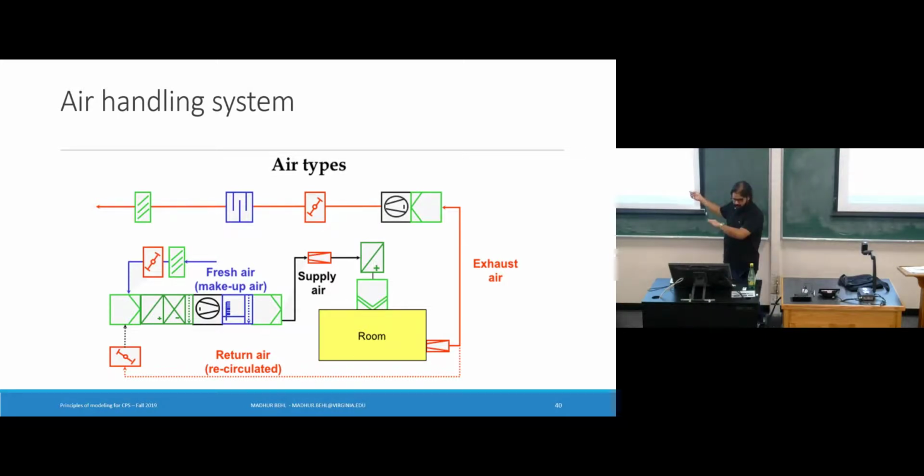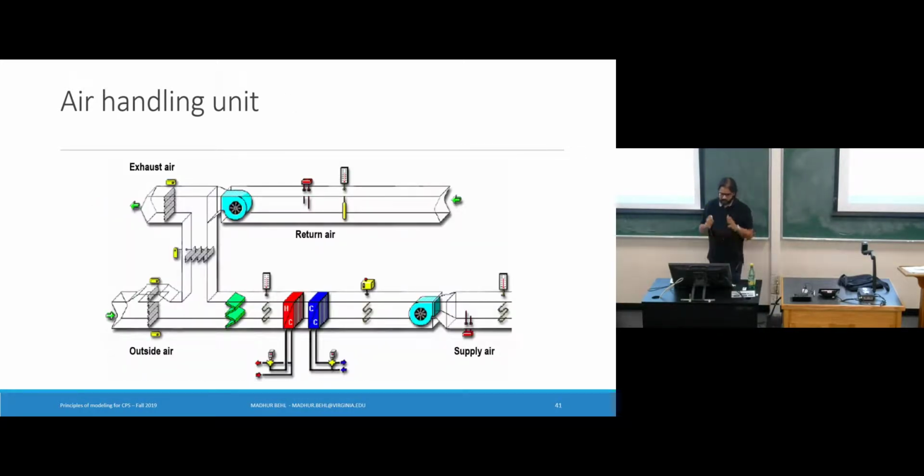So the same story, but in 3D or more detail. If we break down the air handling unit itself, again, outside air comes in. How do you actually condition the air is the next question. So let's talk just about temperature first. Inside the air handler, there are some heat exchangers or coils. So let's say we want to cool this air. What is happening without us realizing is that inside every air handler, we are continuously circulating chilled water. So this is the first transfer from air to a liquid, right?